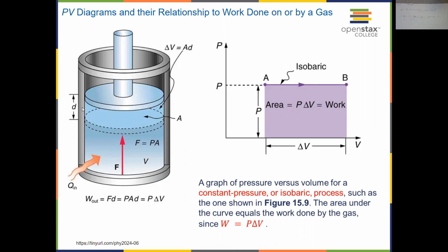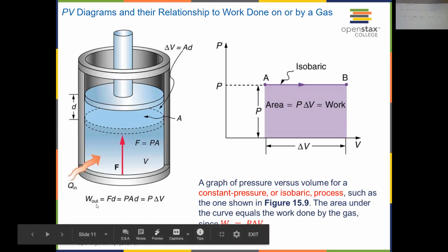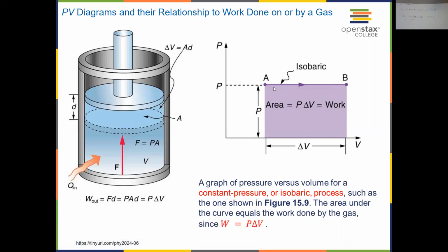So that's equal to the amount of the expansion of the gas system, right? It expands by that amount in volume. So the work done by the gas system is equal to the pressure times the change in volume, delta V, all right? If you look on the graph over here, it's exactly the rectangular area here. And this is equal to the area underneath this curve from A to B under the PV curve, okay?